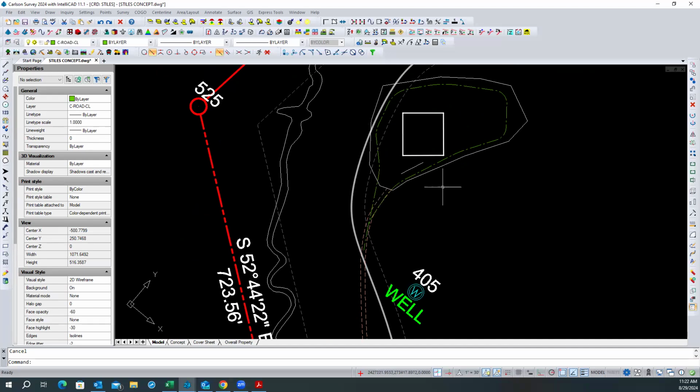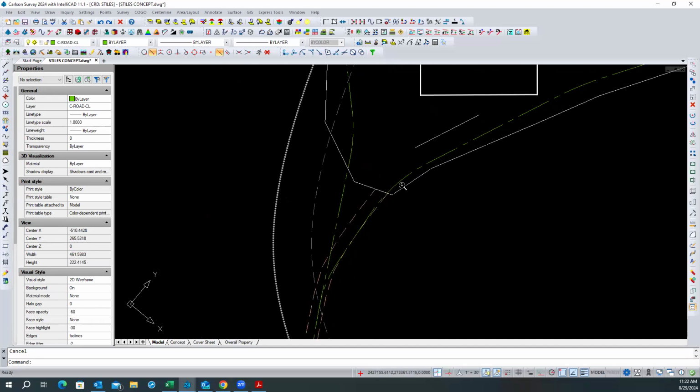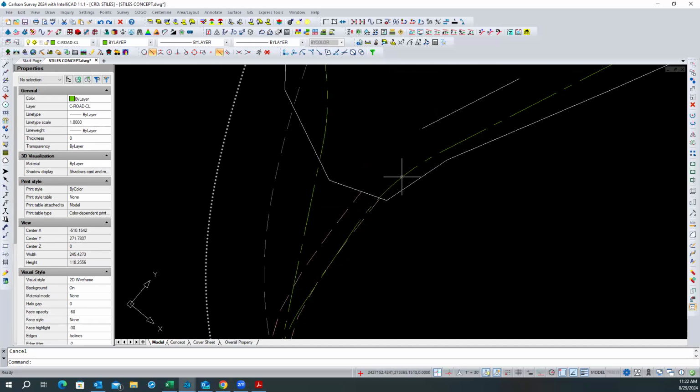So that this slope goes up. I'm just concerned, if we make that roadway, this is the center of my road, and if it's one way, I'm going to need at least a 10-foot lane, 12 would be better. So if I offset that 6 feet, is that, you think, enough? Yeah, he can live with that.